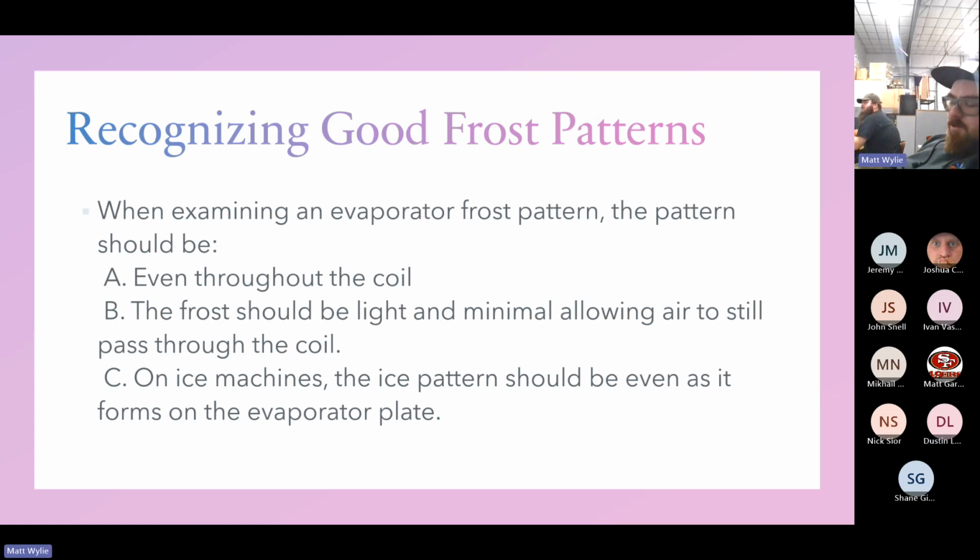And check the charge on your system too, because if you're low on charge, your metering device cannot meter a gas; it can only meter a liquid. So then you'll be off and all that.